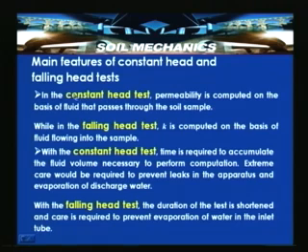The major differences between the constant head test and falling head test can be classified like this. In the constant head test, permeability is computed on the basis of the amount of fluid or permeant that passes through the soil sample, while in the falling head test, K, the coefficient of permeability, is computed on the basis of fluid flowing into the sample.